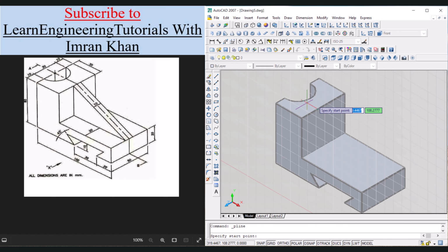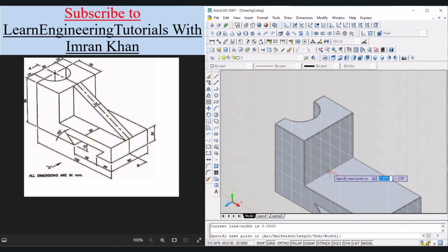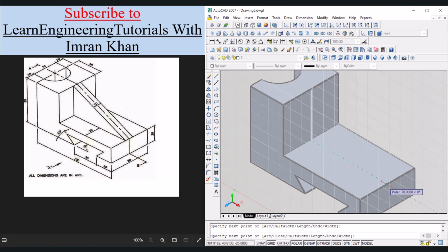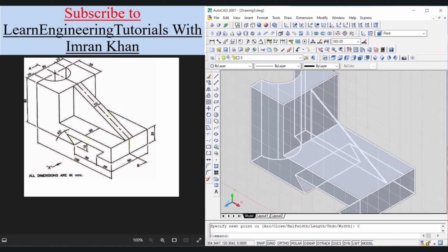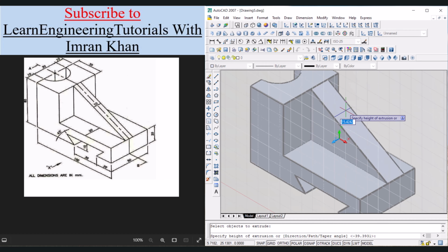Click on polyline, zoom in, bring the cursor to this midpoint and click. Move in this direction, click on the perpendicular, similarly move in this direction as well, and here you have to find the midpoint and click. Now you want to close this object, so write C, enter. Now we will extrude this triangle. Click on extrude, click on triangle, press enter, give the value of 10, enter.